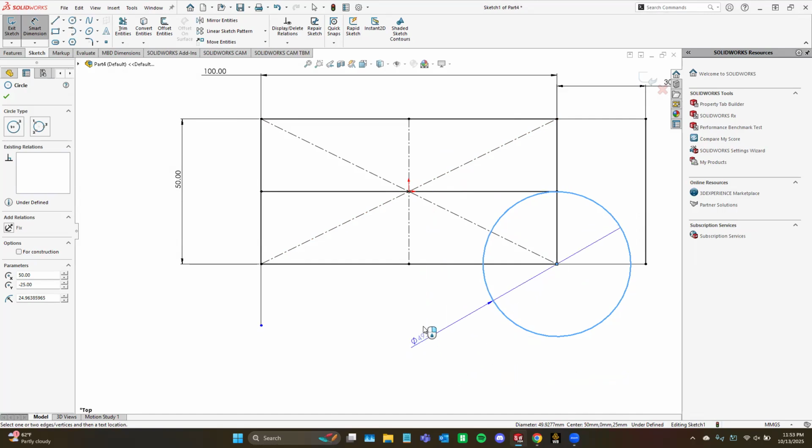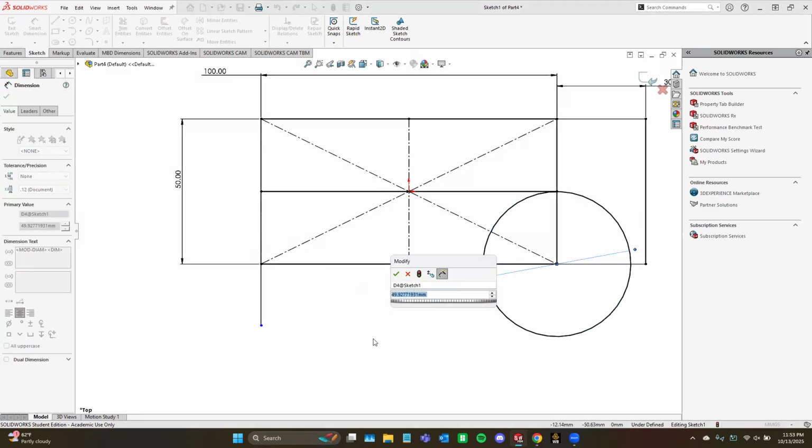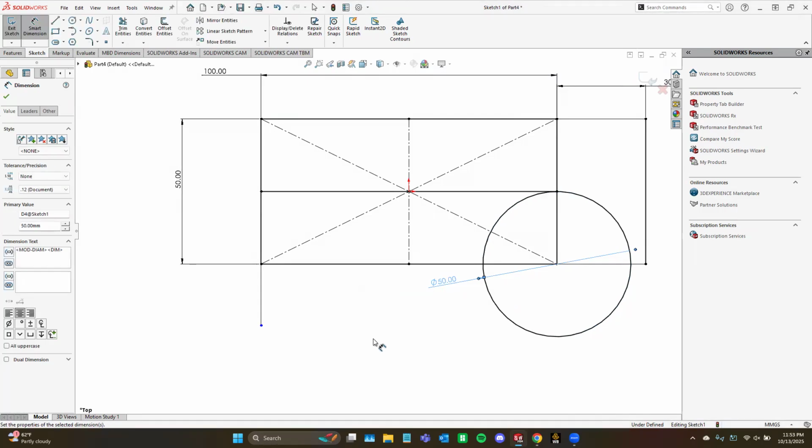the way the dimension is formatted changes based on where I have my mouse positioned. If you want it to be locked in, let's say this way, like you don't like it with the two lines across, you'd rather have it like this, you can right click and it'll lock that look into place. If you want to unlock it again, you can right click again and unlock it, but I prefer it like this. And then just left click to place it down, put in your dimension, press enter, and you're good. Next one is the perimeter circle.